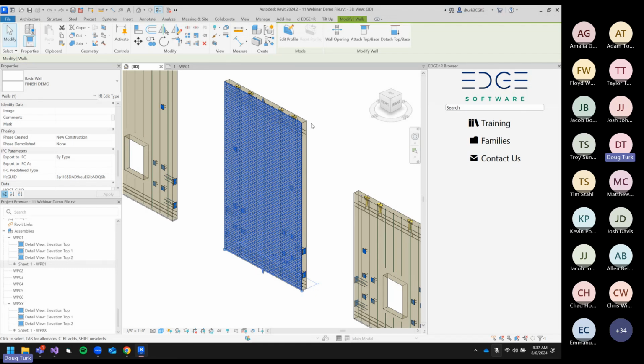There was actually a bug in the code before release 11 causing that not to be the case, and it to basically add any Revit wall that happened to intersect the piece you were assembling. With the 11.0.0 release, this came to our attention because we had several users seeing walls not getting added to assemblies and strange unpredictable behaviors.